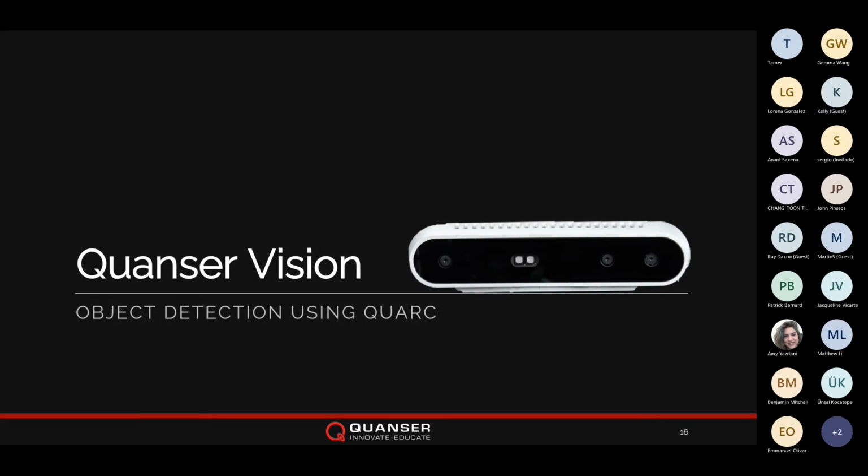In our first demo, we will use the Intel RealSense D415 camera to detect an object of a specific color and track it around the image. This camera is the one that appears in the slide, and it appears in our QBot 3 and our QArm products and includes an RGB lens as well as an infrared-based depth estimation. The goal of the first demo is to introduce you to a few of the common blocks for vision, as well as introduce HSV and image thresholding.